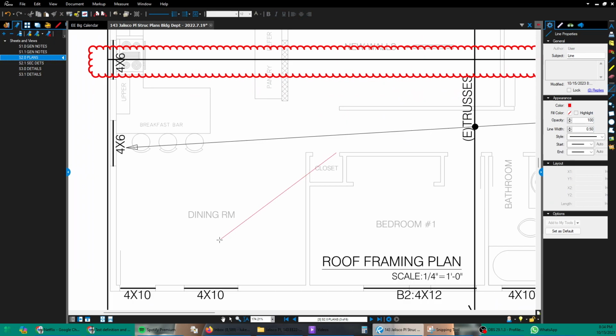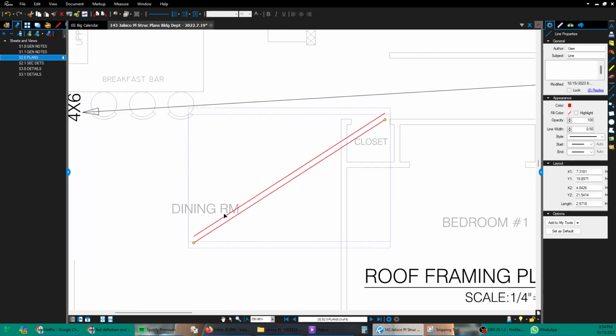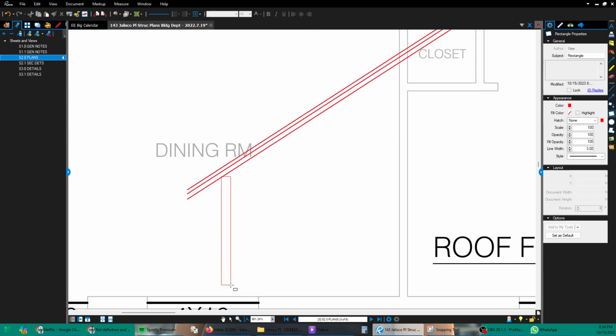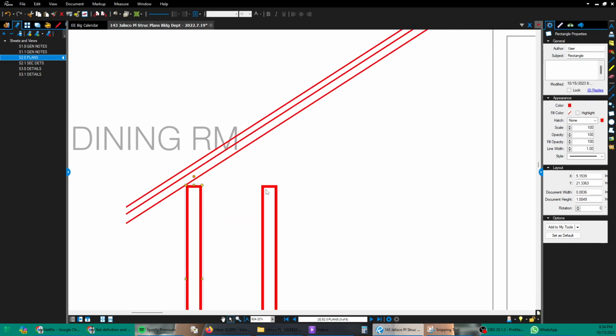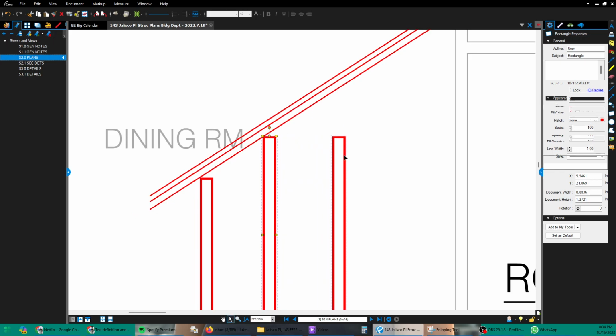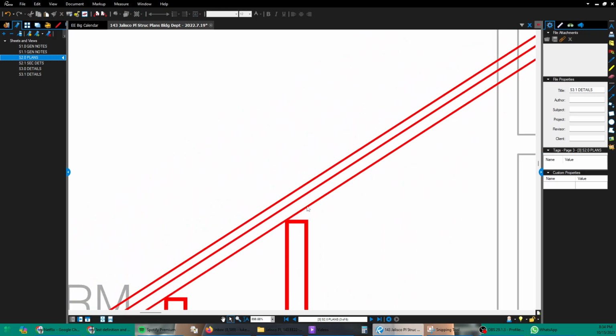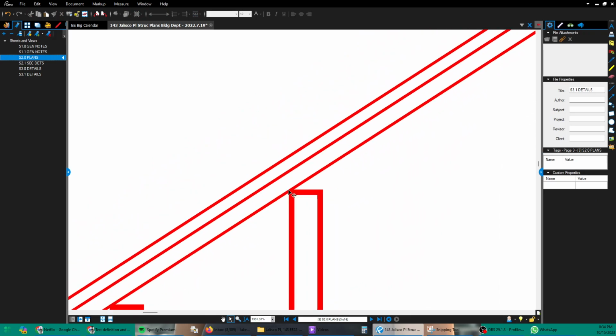And then you would have roof sheathing, being plywood, that would go like this. And the trusses would go like this. Let's fix that. You'd have a truss, and then another truss, and then another truss that was slightly taller. And notice how the truss isn't fully in contact with the roof sheathing. That's an awkward connection where the roof sheathing is bearing on the edge of the truss.